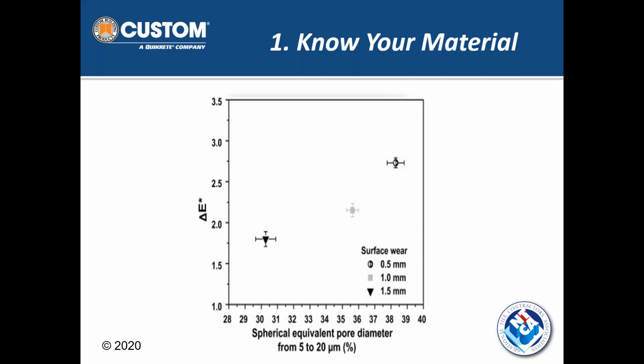That is what will either cause or lead to grout staining and staining in general. But if you remove 1.5 millimeters of material, the potential for staining, in other words, removing all of those pinholes and pores, is dramatically reduced to where, again, those are the tiles you typically run across saying, wow, I don't have an issue at all with grout staining or staining at all with porcelain. That's the difference.